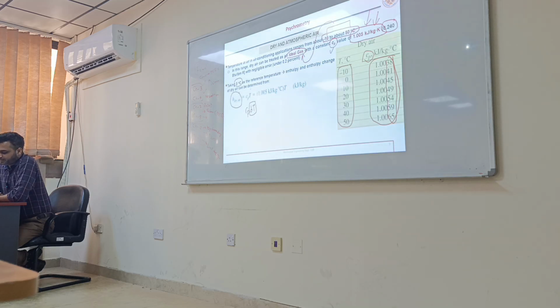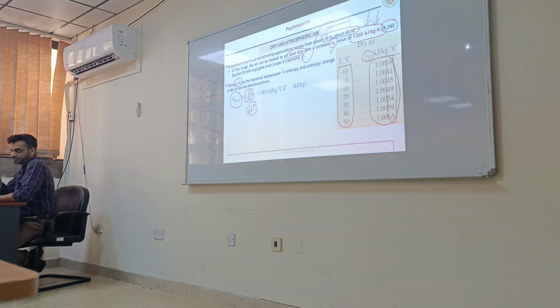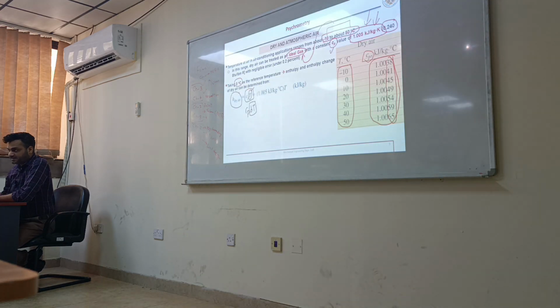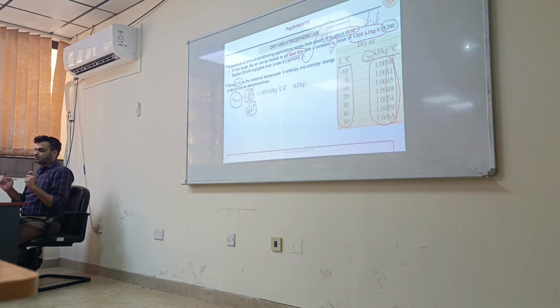So that's why it is not written as dT, because one of the T is 0, the other is any other temperature. So in this equation, when I am writing dry air enthalpy as Cp T, the only T means the other T is 0 Celsius. So it means this single T which is left here is Celsius also, right?